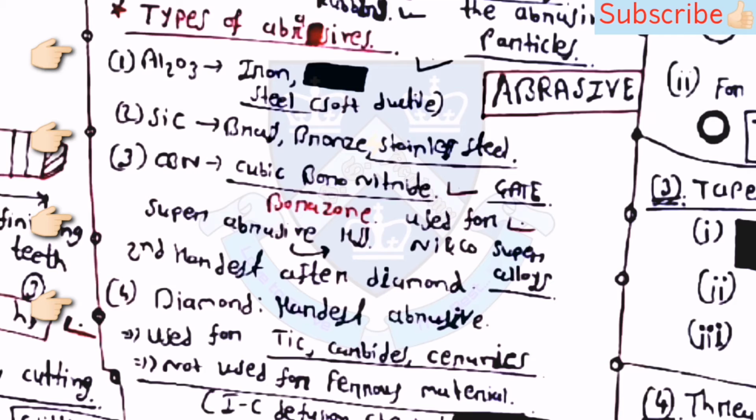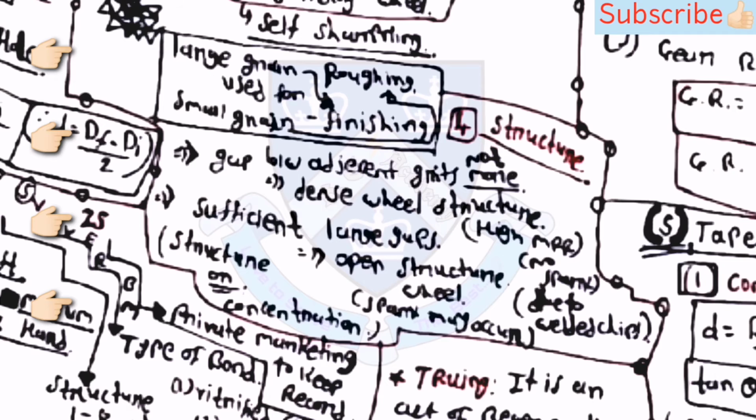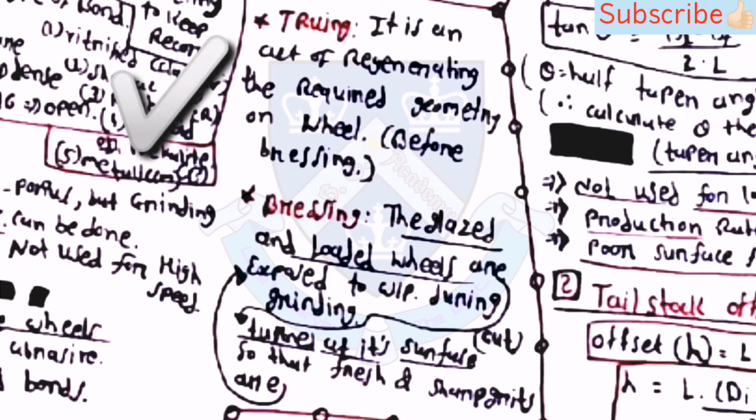Al2O3, SiC, CBN and diamond. Then there are some properties for the grinding wheel, like grit number is inversely proportional to the grain size, and for grinding hard material, the soft grinding wheels are used. Then there are structures, dense and open. And there are two important processes, like truing.